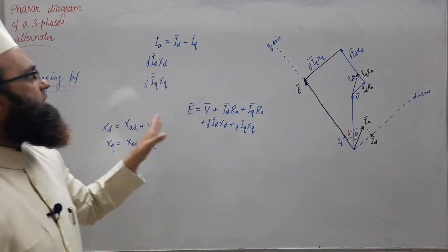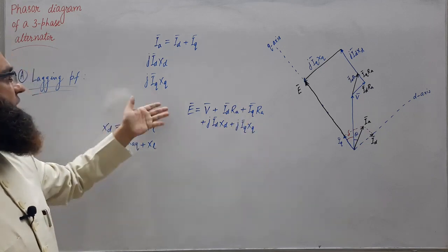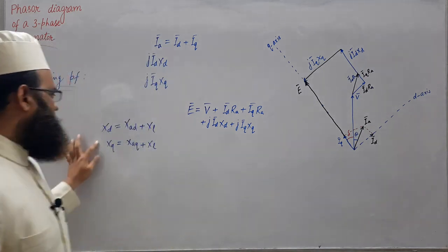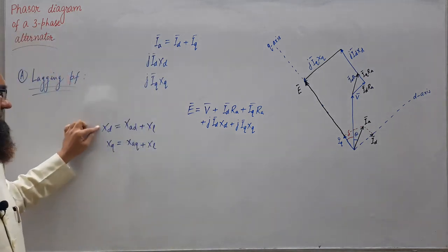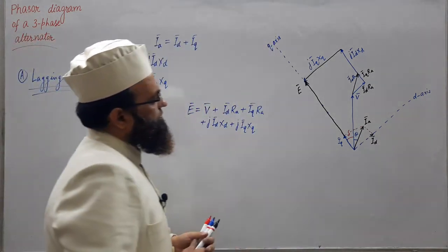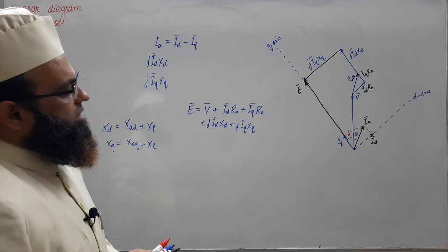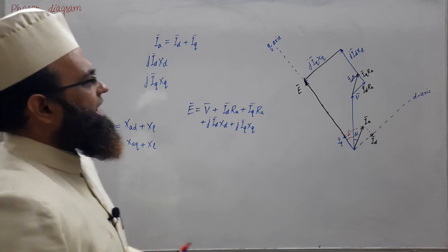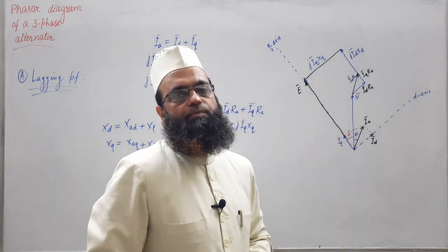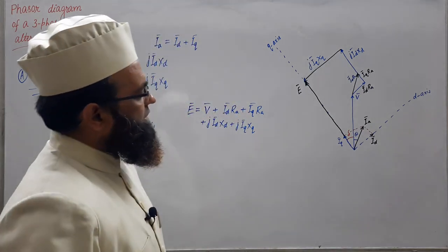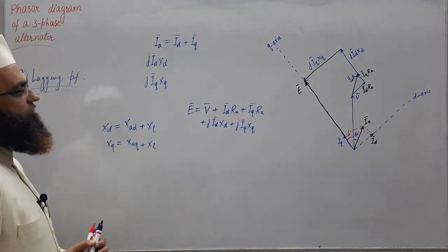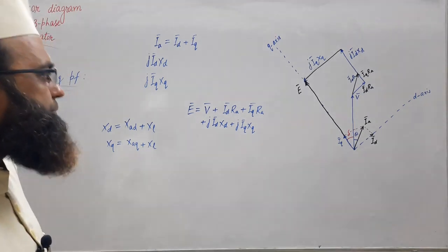This way we have drawn the phasor diagram of a salient pole machine. We have written the direct axis and quadrature axis components for salient pole. For cylindrical, these two reactances, as discussed, are the same, as we have a uniform air gap. What will we do when delta, the power angle or load angle, is not known? If delta is not known, then we have one alternate method.